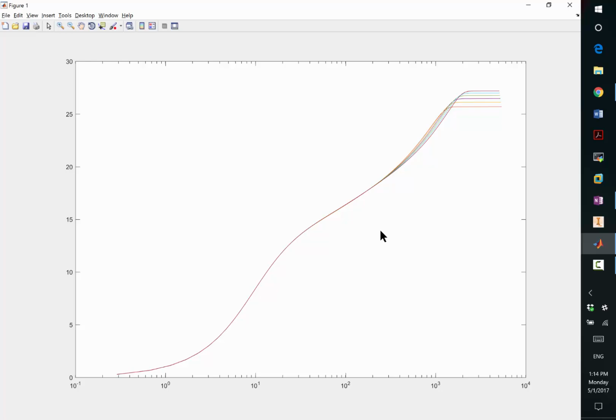But UE being uniform, is that physical? Or is that imposed? Yeah, UE being the same is imposed because the DNS is simulating a flat plate. It's simulating the boundary layer over a flat plate. So UE is pretty much the same along the way, or at least the simulation tries to control UE to be the same. Okay, so this shows the inner layer.